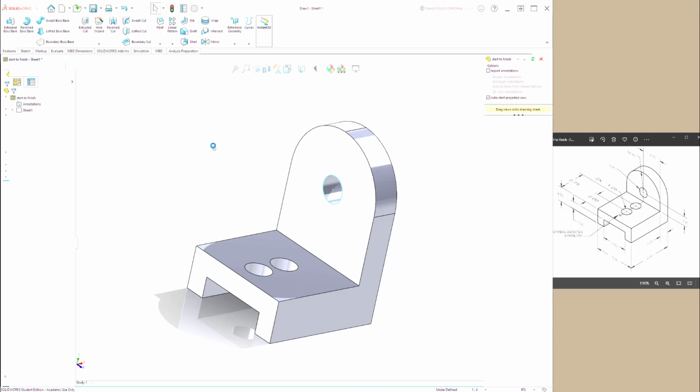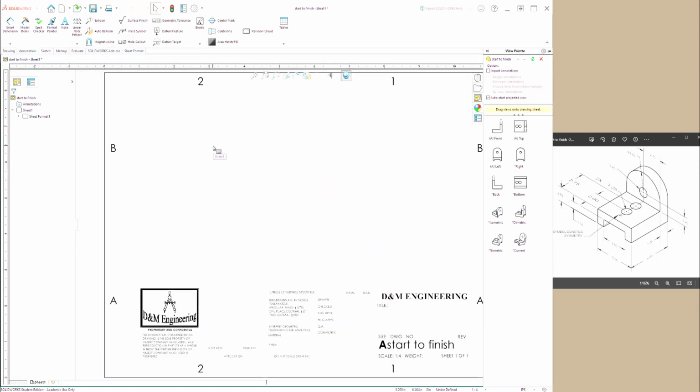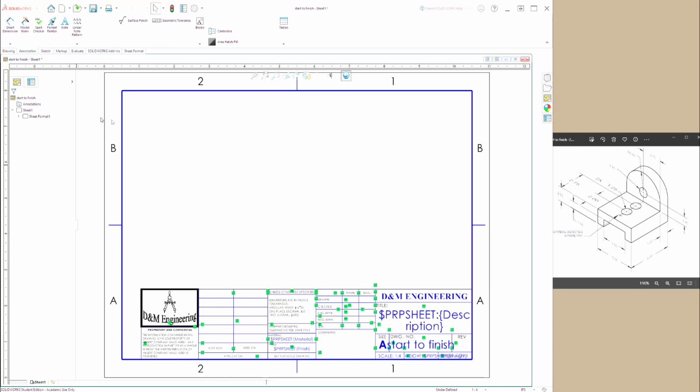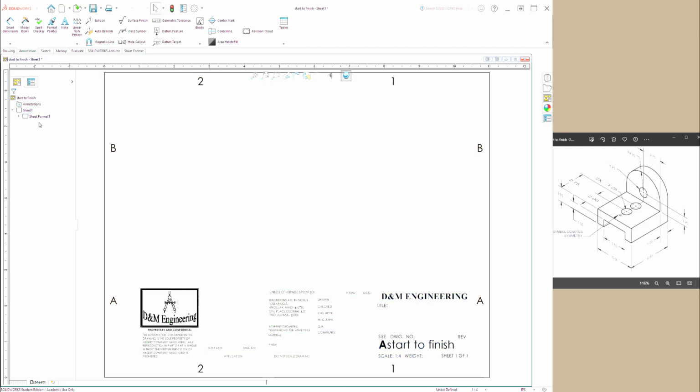With the inch ANSI drawing, it's going to come up and give us some basic information associated with our drawing. We can customize and create our own title blocks and so forth. The sheet format, you can edit the sheet format, which I did, with a right mouse click here. And right now the sheet is an A size sheet. We can go ahead and edit the format of the sheet, which means by editing the sheet,